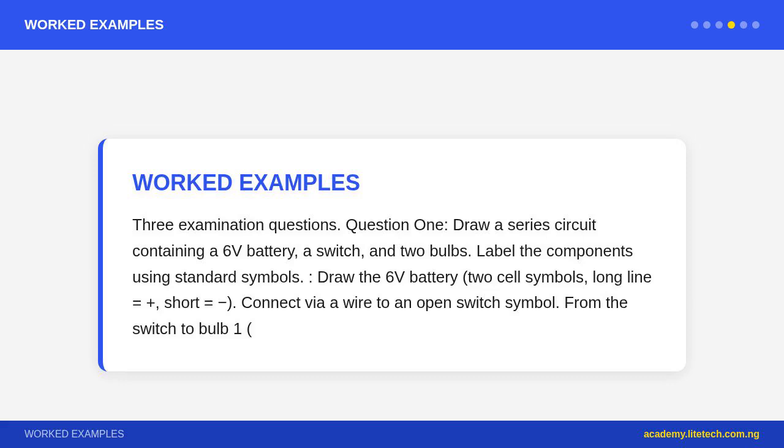Labeling conventions. Always label component values, if given, current directions, conventional, from plus to minus, ammeter readings, voltmeter positions, across components, not in series. Wires are drawn as straight horizontal/vertical lines. Diagonal lines are avoided in formal circuit drawings. Use pencil and ruler for neat circuit diagrams. WAEC examiners penalize sketchy, freehand diagrams.